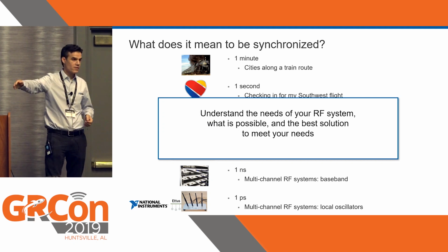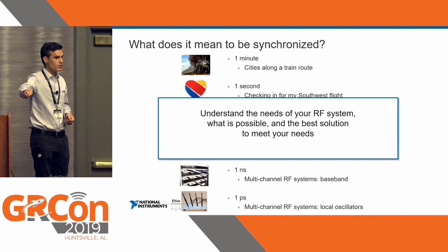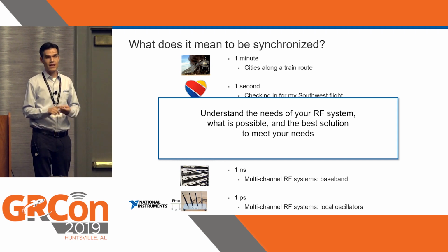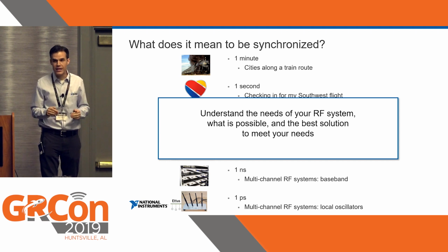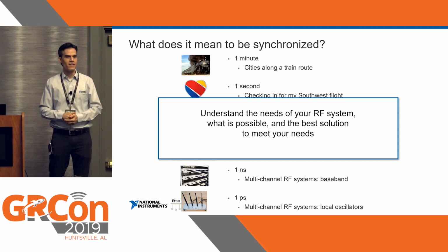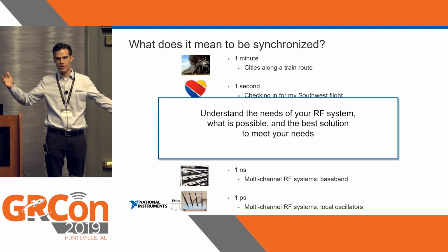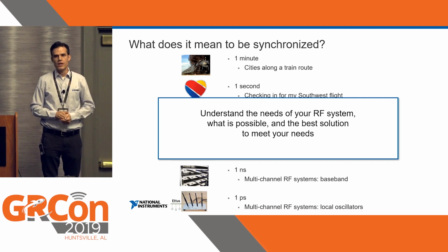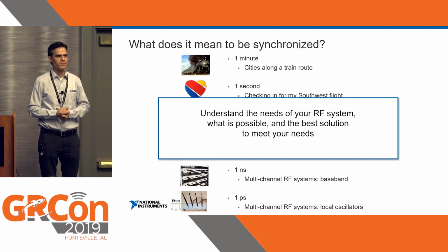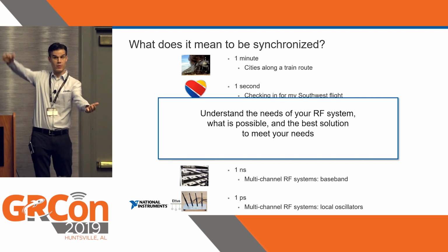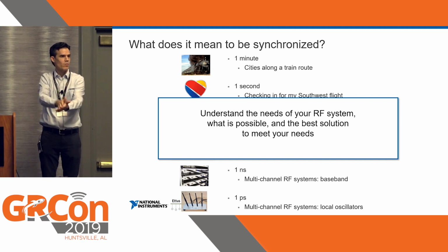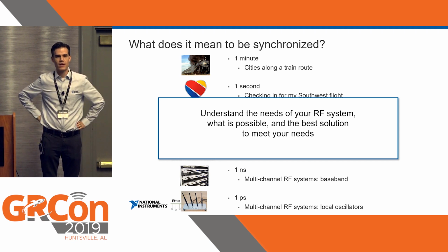Because if you are trying to align everything down to the picosecond, you can do it, but it's expensive, it takes a lot of time, it's extremely temperature unstable, you breathe on it, right, and the thing shifts. And you go for coffee, you come back, and it's all shifted out of phase again. And so you don't want to go for too little and say, oh, a millisecond's probably good enough, and then you end up with a beam forming that's this wide. But if you really need that precision, then it's going to take some extra time and effort, but it is possible.